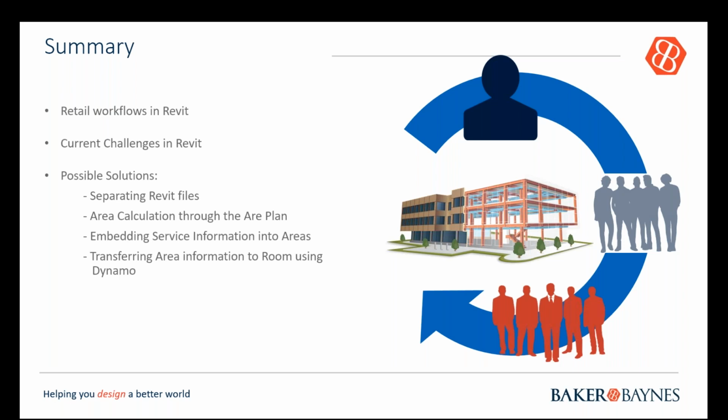The first one is file management, which is separating your Revit files into interior, your main model, and your site file, and linking those files in so that you have information stored on each of these. We then also use the area plan tool to calculate areas a little bit more precisely. The area boundary tool allows us to specify the line from which the area needs to be calculated.